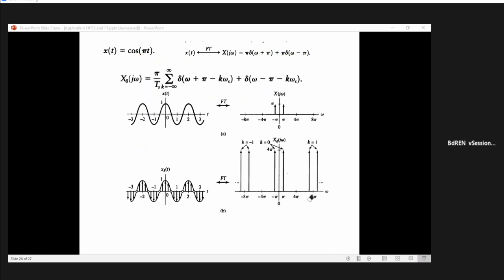If we have thin pulses, your signal will also appear as a series of thin pulses. Then if they are Fourier transformed, your pulse signal will generate a sinc function like frequency spectrum. So if they are added together, they will generate your output.